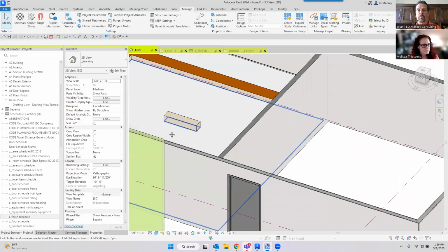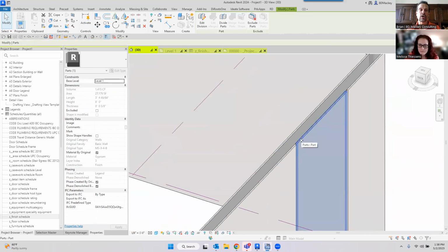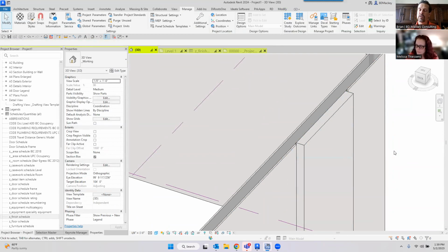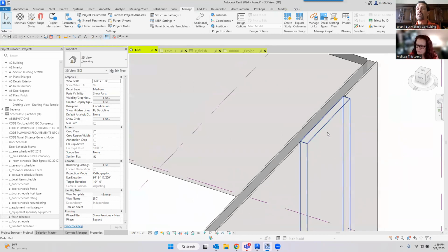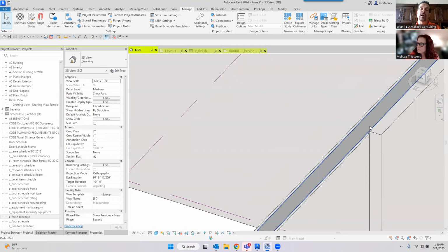Horrible example on a finished floor, but like over here on the wall, ooh, I wanted this one wall piece to be thicker. This chunk of concrete needs to bump in, this concrete needs to bump out, whatever. It's still a basic part of the original wall, but now I've said make this one part thicker. You can then subdivide the parts behind it and merge parts. So you can even show like the concrete wrapping back in at openings if you need to.